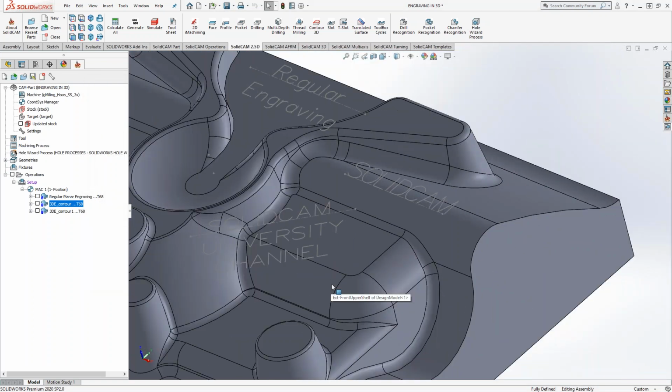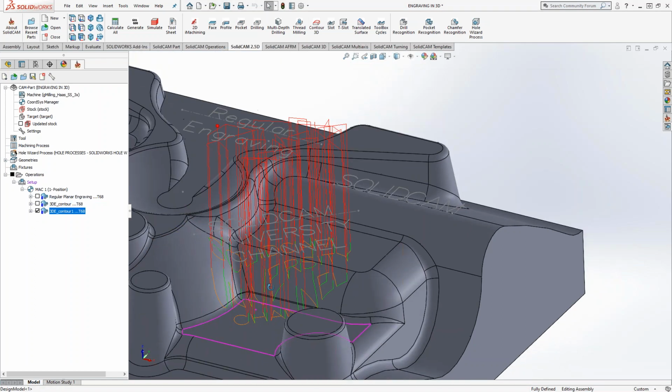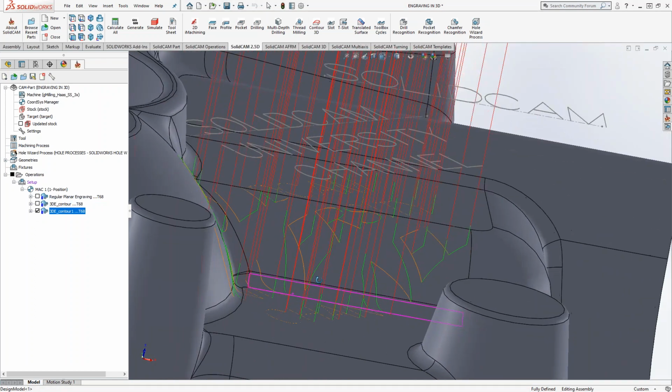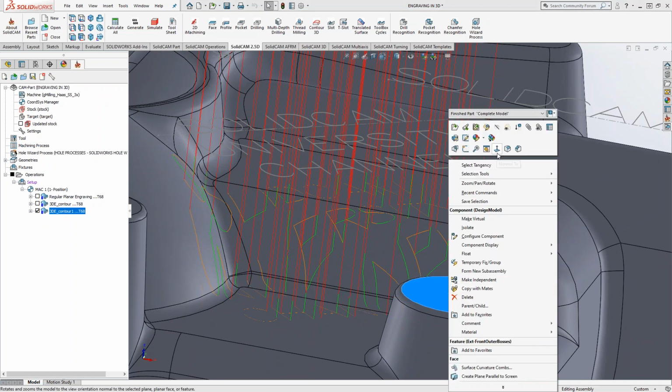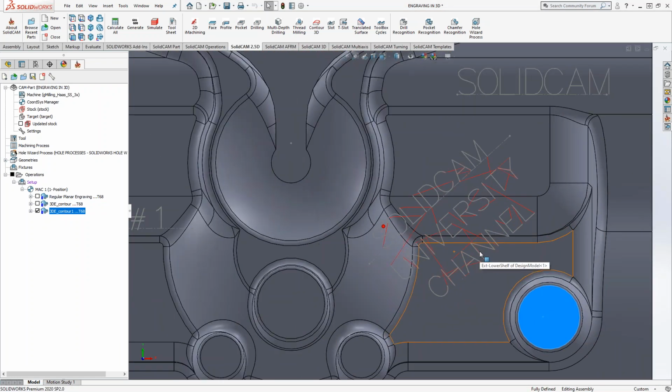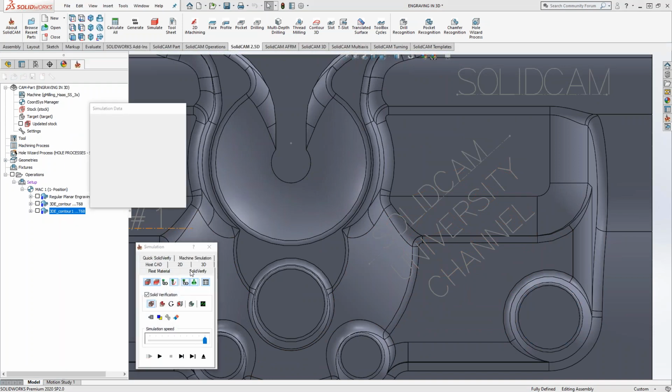So this kind of goes back to the HSS versus HSM discussion. If I need to target a particular surface, I would use HSS. If I need to just kind of do it overall, I can do HSM. Whereas here, it's the HSM side of things. I can just choose the solid, and then the projection of my toolpath happens on all the surfaces. Now this one kind of looks a little warped until I look at it from the top view. And then you can see that it actually is doing the projection of the toolpath. If I just go into my Solid Verifier real quick.